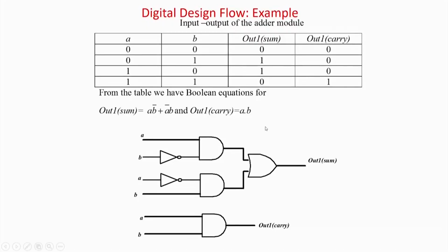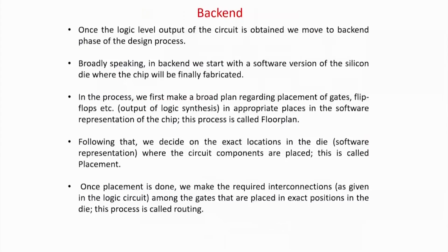So this is the example of a gate level synthesis. The simple adder, as you know, has inputs A, B and carry, and you just require a Karnaugh map to get the circuit as the output. But if it is very large, Karnaugh map and Quine-McCluskey will not be able to do it. You have to use some heuristics called, as I told you, Espresso.